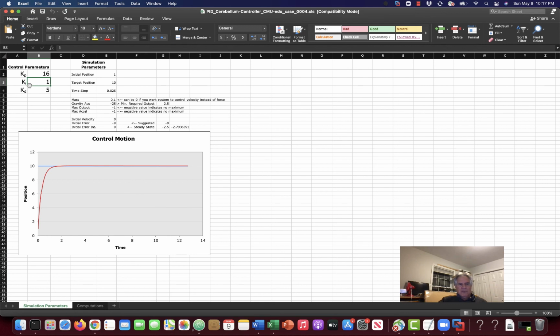And there's a little bit of integral term there to remember this error, so we do close all the way into the target value. But also because of the oomph we have and because of our caution on the overall velocity, we wind up with a nice system that converges and does not overshoot.